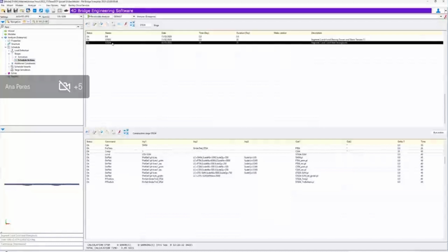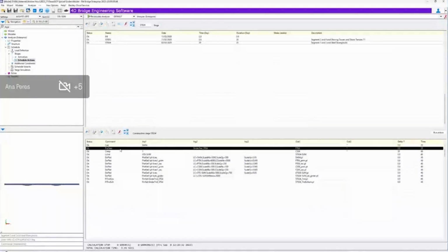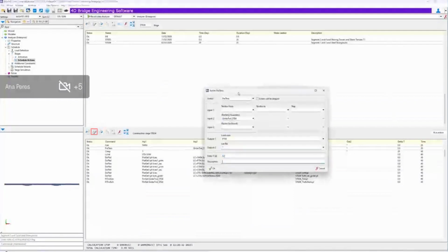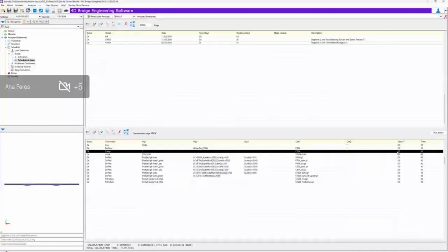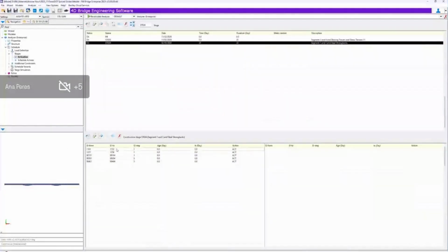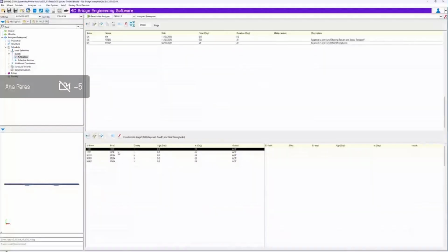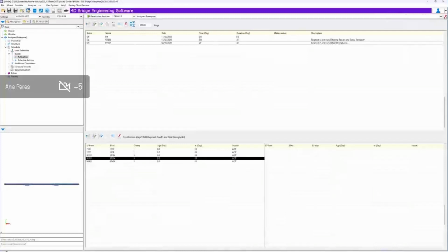So in this case, the stage 4, it's considered the self-weight, the pretension schedule action for activating the pretension tendons, and the creep. At the activation, we see now the I-girder end segments, the definitive bearings at the abutments, and the steel strong backs activated at the extreme spans for transferring normal and shear forces.